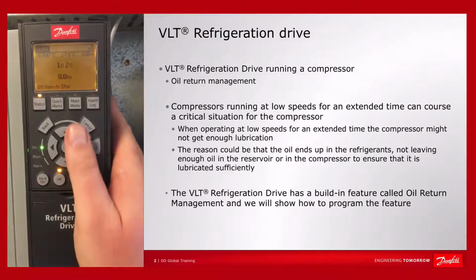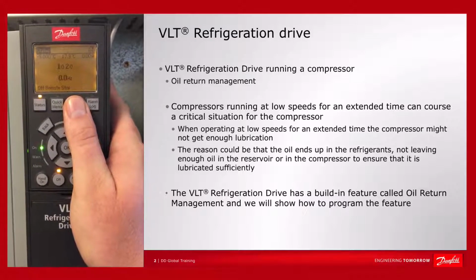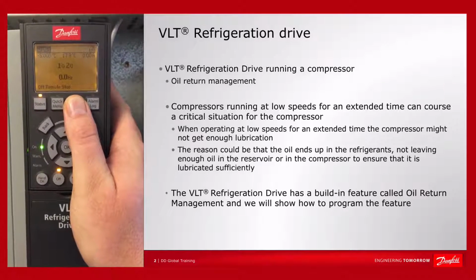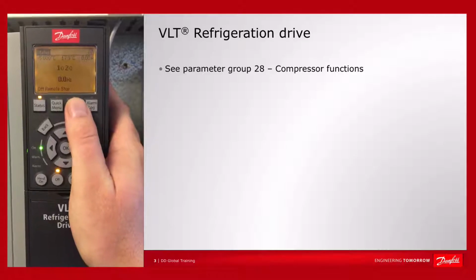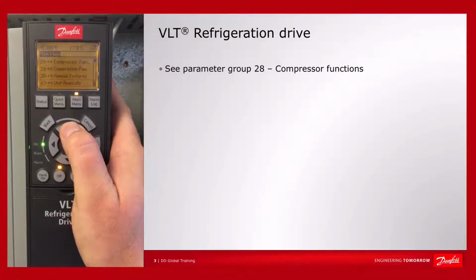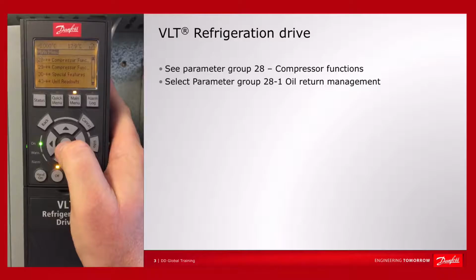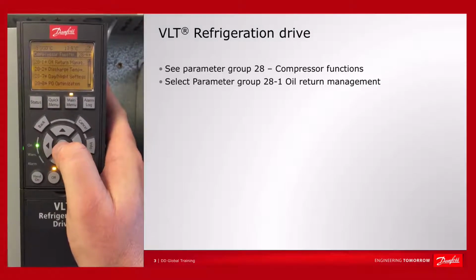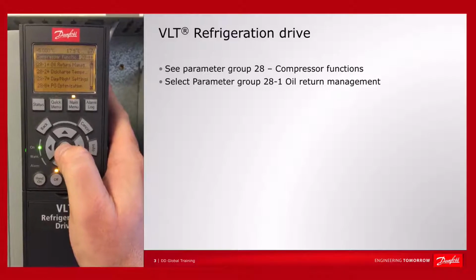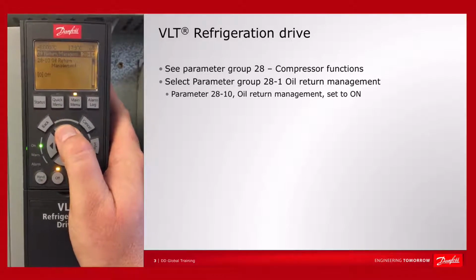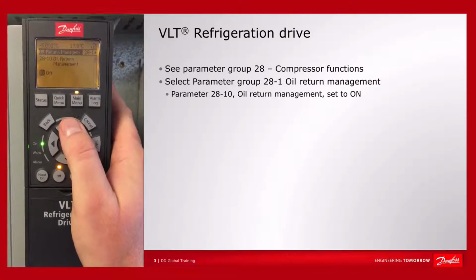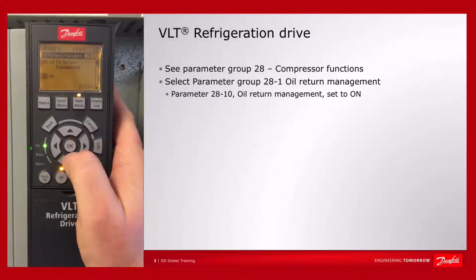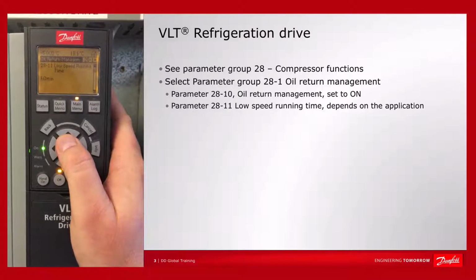The refrigeration drive has a built-in feature called oil return management, and I'll show you how it's programmed. If you enter main menu, go to parameter group 28, compressor functions, and select the subgroup 28.1 oil return management, you can program the feature very easily. The first thing is 28.10, and you must enable the feature, select on, and then you go down to 28.11,